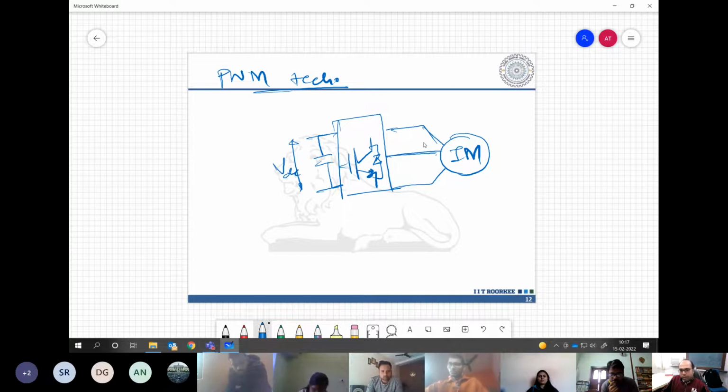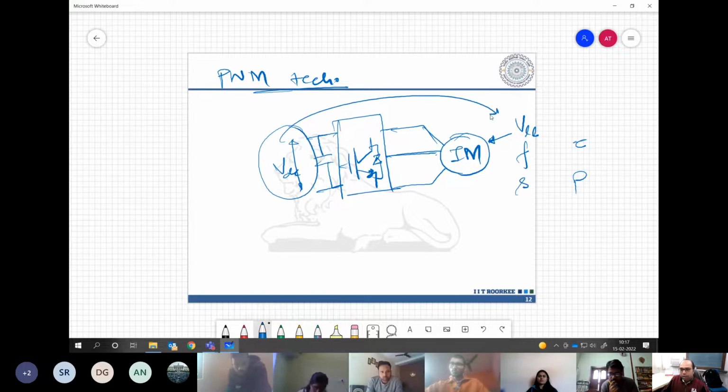When we are operating any motor, the nameplate ratings of the motor are fixed. Let us say the line to line voltage is given, the fundamental frequency is given, rated slip may be given, rated torque or power may be given. Now, can we have any amount of DC bus voltage operating this motor? For example, I take a 400 volts line to line motor, RMS value. Can I operate this motor with just 100 volts on the DC bus? Can I have this condition?